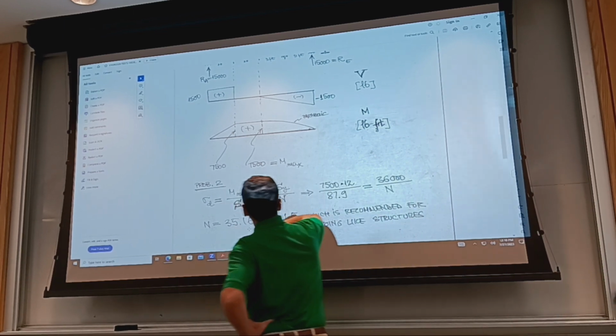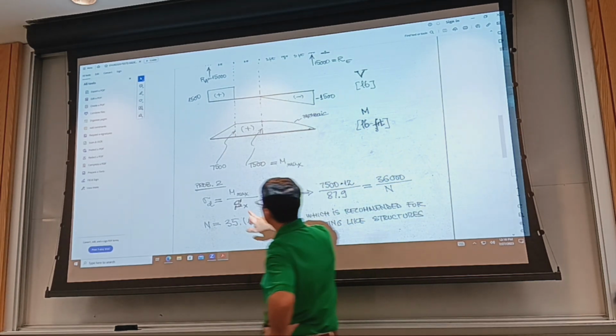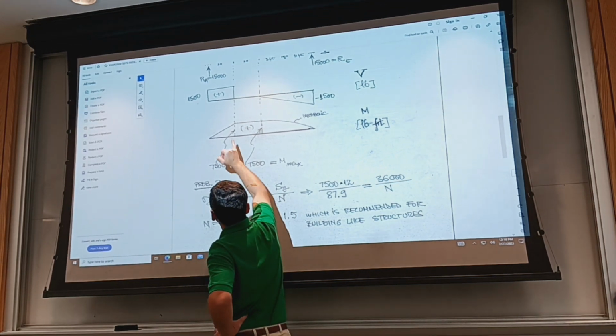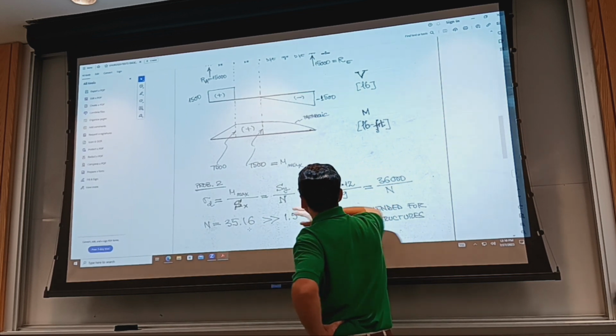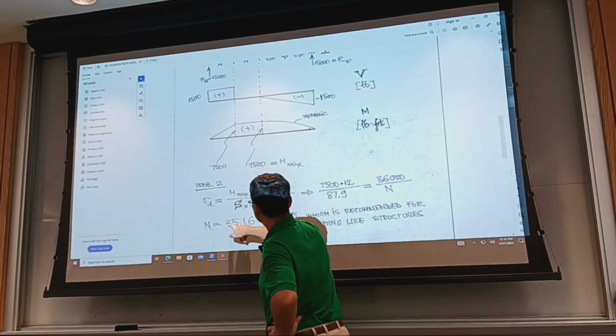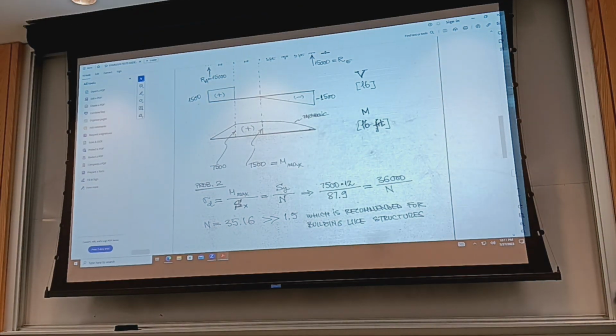I stated the flexure formula was the section modulus, the maximum moment over this section, between B and C, section modulus in the table, solve for the design factor, and this becomes 3.5. Okay, I made up this problem, so it was a bit too big. Sometimes you ask yourself, is it really? It's an unusually big design factor.